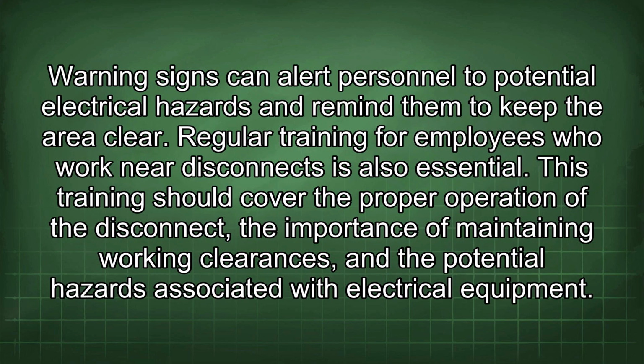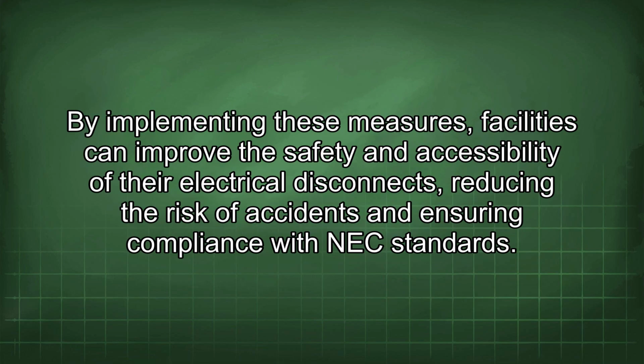Warning signs can alert personnel to potential electrical hazards and remind them to keep the area clear. Regular training for employees who work near disconnects is also essential. This training should cover the proper operation of the disconnect, the importance of maintaining working clearances, and the potential hazards associated with the electrical equipment. By implementing these measures, facilities can improve the safety and accessibility of their electrical disconnects, reducing the risk of accidents and ensuring compliance with NEC standards.